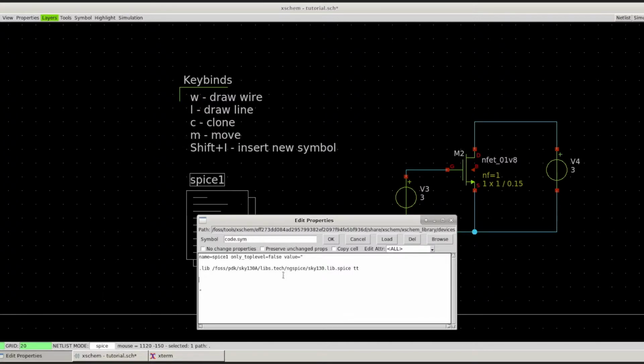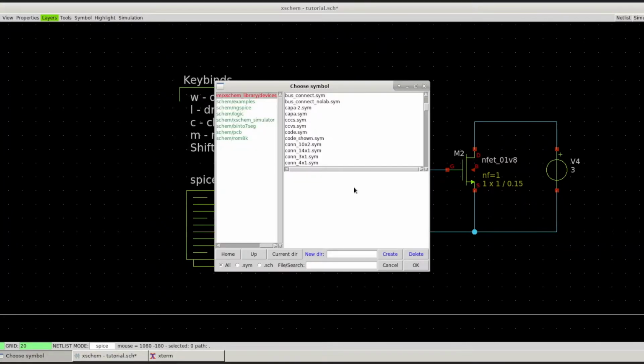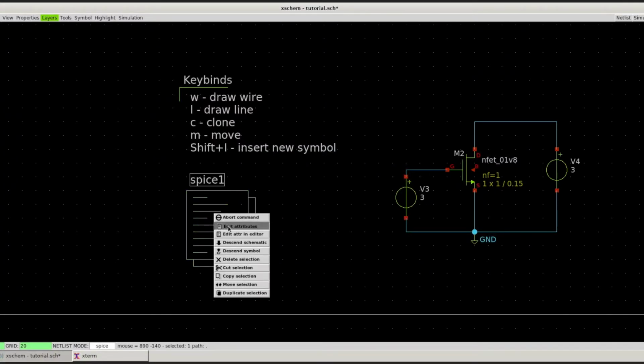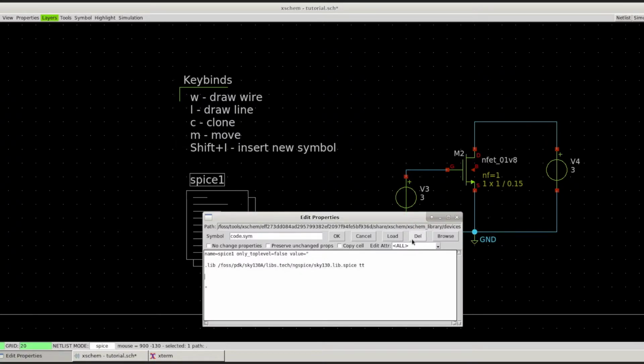Okay, after this, we're going to focus on our SPICE script that we want to run on the circuit here. And actually, I forgot one thing. We need to probably add a ground. Okay, so if you've read the ngSpice manual, then you already have a good grip. It's just like any other SPICE language. We're going to create a new control block, and we want to make sure that at the end of the execution we save all results. So we'll go ahead and do a .save all.